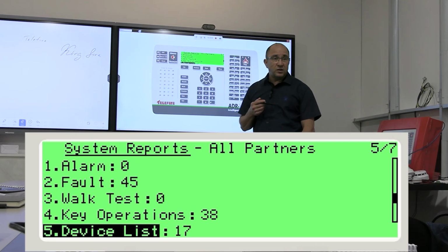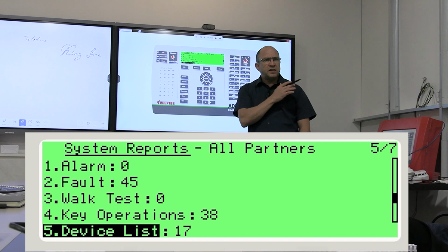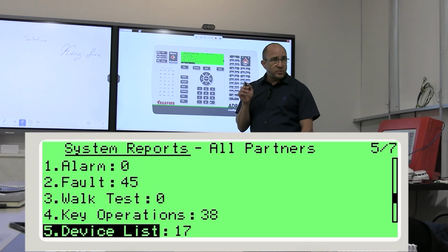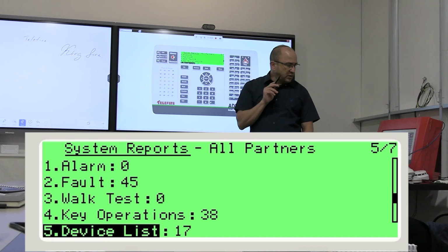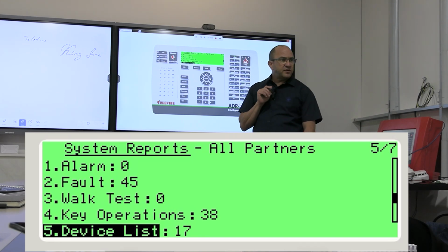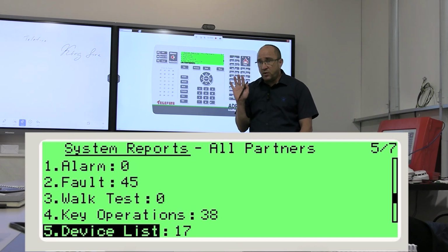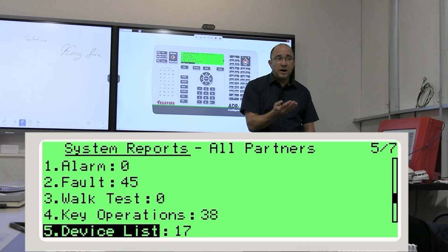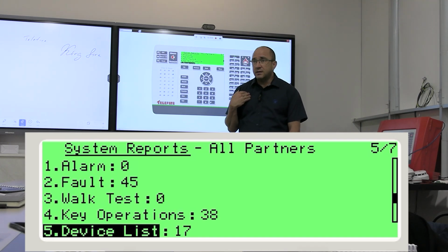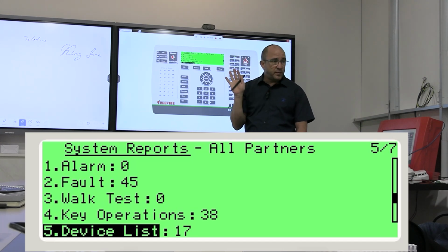Just now we'll do diagnostic and we'll tell the system, please look to see if everything's okay. I promise you, if you connected it correctly, he will tell me that, look, I found address number 5 in the system, but it's not programmed. Maybe you know about it, maybe it's my mistake. But here, he takes a flag and he tells us there's a problem.